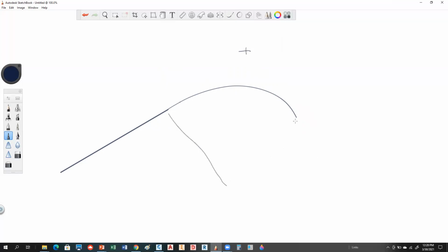Well, on any type of curve, you'll have what's called a radius point. A radius point. So that's the point where the two radiuses meet, and that defines that. So this would be your radius, and that would be your radius. Everybody kosher with that? You see that? So when you want to know what the station is to this point, what you do is you construct a line from the point that you want down to the radius point, and that's referred to as a radial line. Okay, so this line is called radial. That's a radial line.